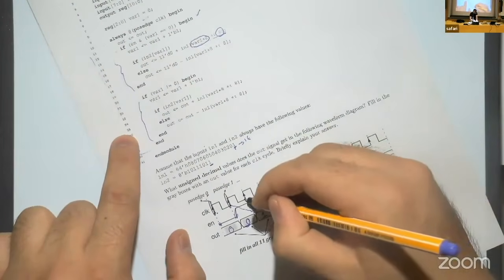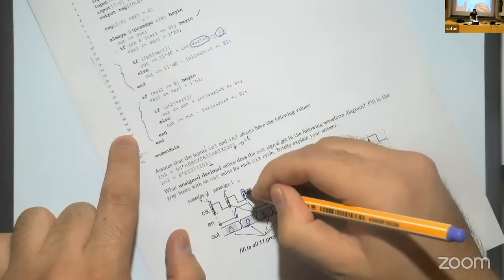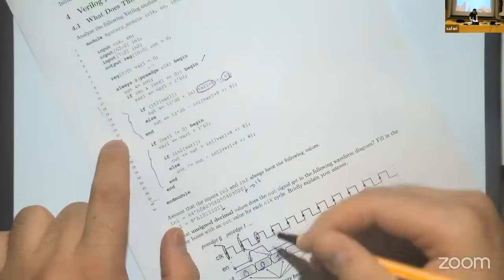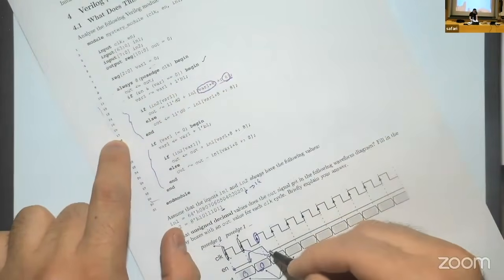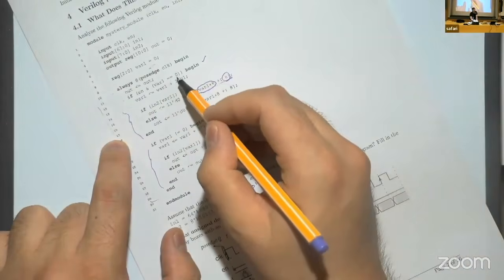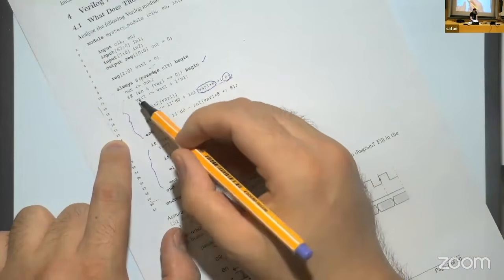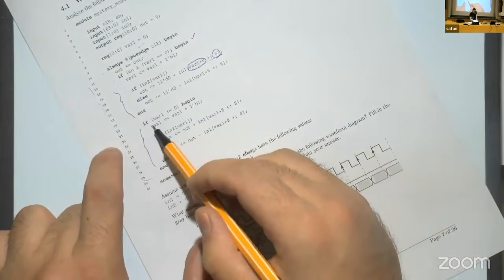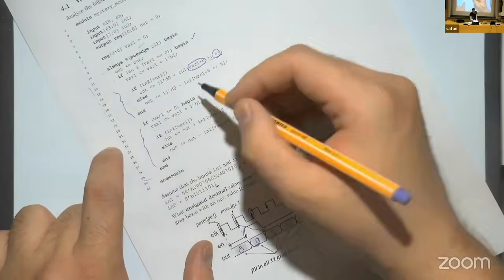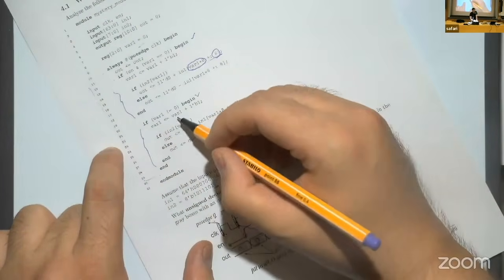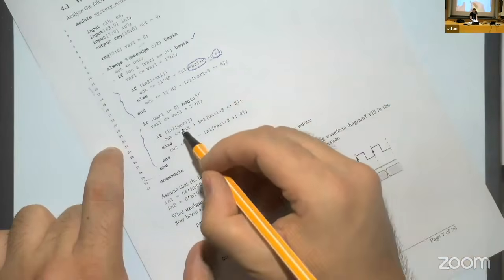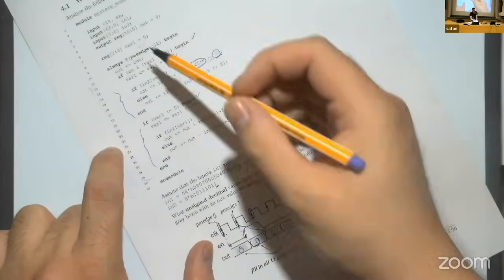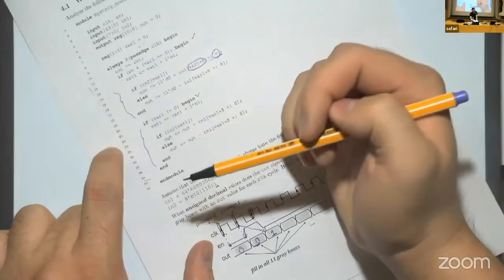When we execute this one, variable 1 is 1 now, and out is 1. Let's execute that one again. Enable is now, it doesn't matter, variable 1 is 1, so we don't go into that block. And we check this if, the 21st one. Variable 1 is not 1, so now we go into that one. Variable 1 becomes 2 here, but it will be updated after this always block is executed.